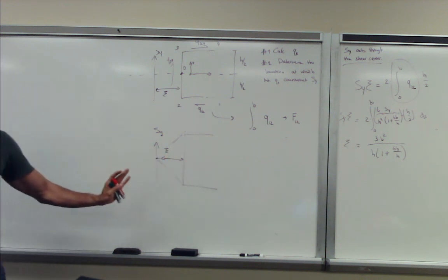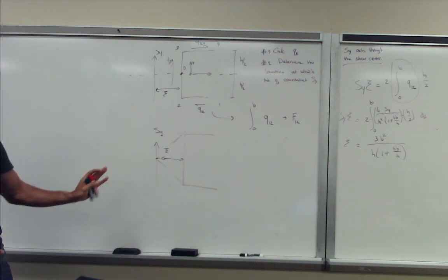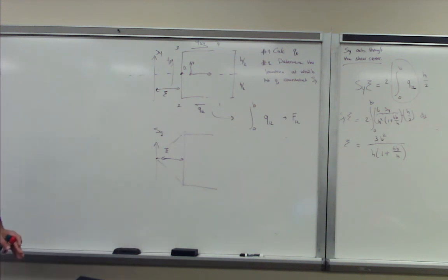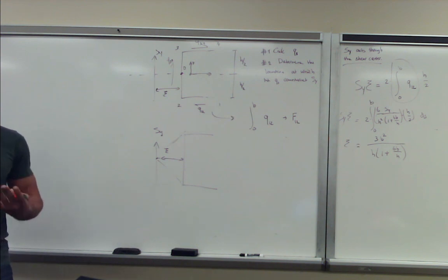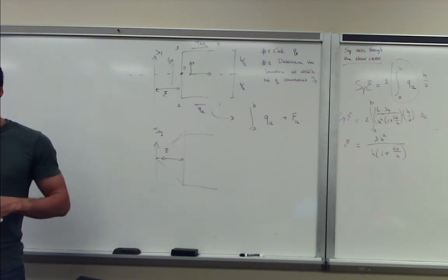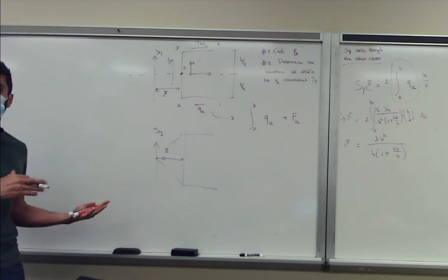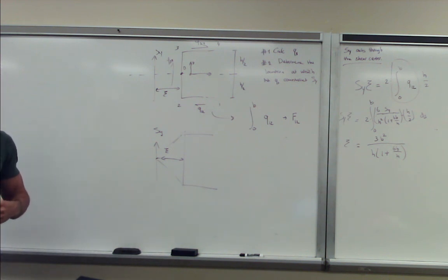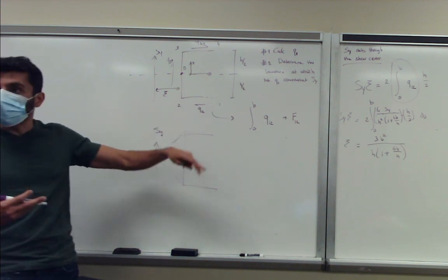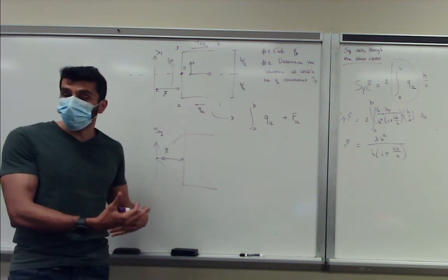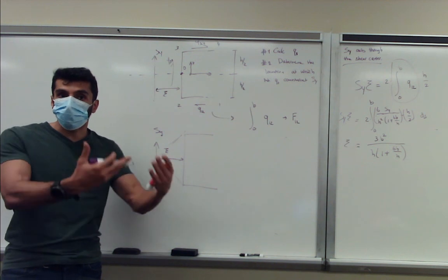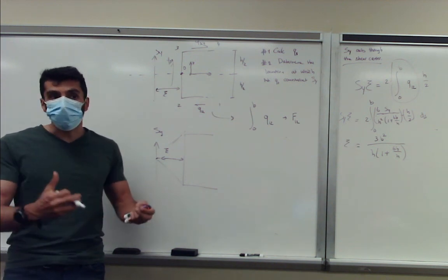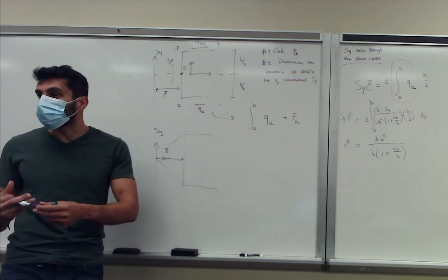In some of these examples, when the shear center is outside of your cross-section, we're talking about a mathematical point of view: where should I apply my shear force to have zero twist and twisting coupling? That way I truly just bend, and then I can use my standard equation to see what my shear flows are in the structure. Once I know my shear flows, I can determine the shear stresses, and once I know the shear stresses, I can determine if there's failure or not.